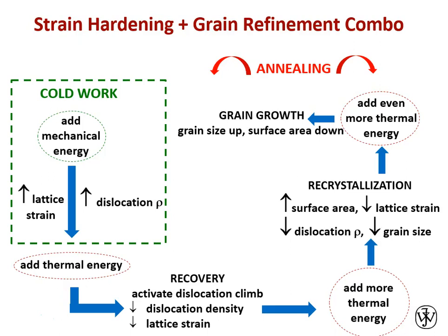The material still has a tremendous amount of energy in the form of elastic strain. You have a lot of atoms that are not in the position that they want to be relative to their equilibrium position, so we have that potential energy all locked into the material. One thing we can do with that is create more surface area within the material. Now, this isn't like a metal air surface like we would see in fracture. We can form more grain boundaries